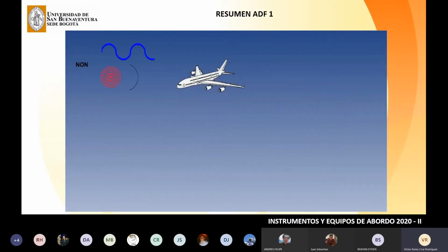Two types of modulation characteristics are commonly used for NDBs: N0N-A1A and N0N-A2A. The N0N part of the signal is, as we saw earlier, the continuous carrier wave, and it is ideally suited to enable the ADF equipment to establish the direction from which the signal is arriving.